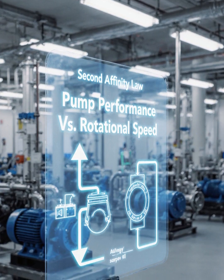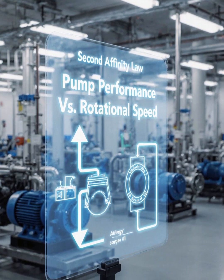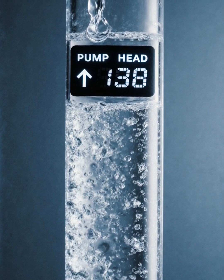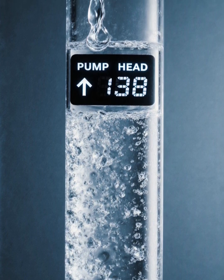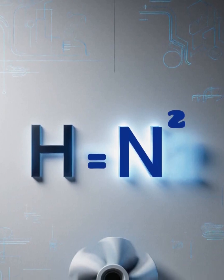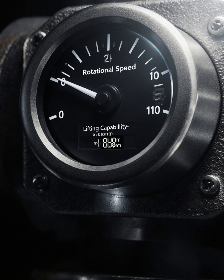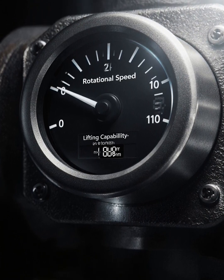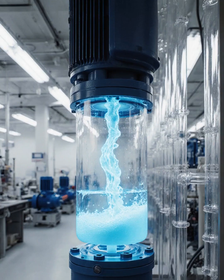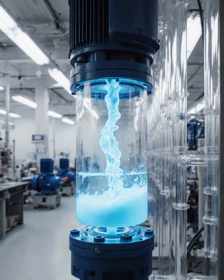The second affinity law describes the relationship between pump performance and rotational speed. It specifically addresses the pump head, which is the vertical height a pump can lift a fluid. This law states that the pump head is directly proportional to the square of the rotational speed. Thus, a small change in speed significantly impacts the pump's lifting capability. The relationship between pump head and speed is crucial in fluid dynamics.